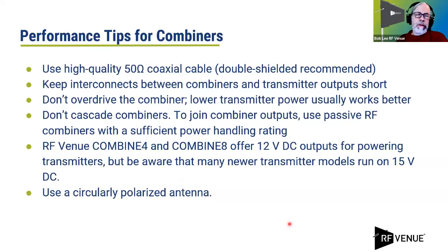Next, don't cascade combiners. Like Rich said, don't go from the output of a combiner into the input of another combiner. That's going to really overdrive the input of the second combiner. Just use passive combiners that have a sufficient power handling rating.